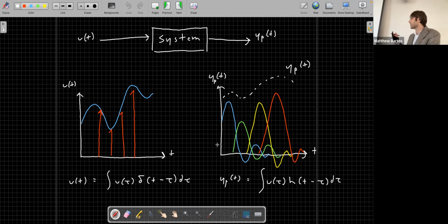And as I mentioned before, often in dynamical systems or in civil infrastructure systems, we're interested in obtaining the impulse response for a system or approximating the impulse response for a system. So this is often used in the domain of what's called system identification, where you take a structural system, for instance, and hit it with an impulsive input. So you literally hit it with a hammer sometimes in the lab. And from that, you can characterize the system's impulse response and thus determine its response to any arbitrary input like an earthquake, for instance. Okay, so it's important practically as well as theoretically.